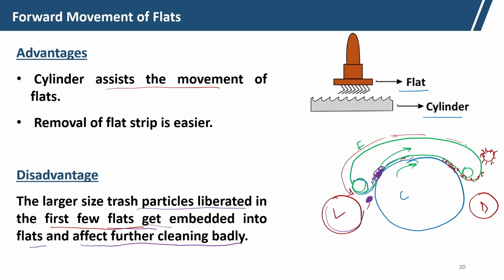If this large size particle is embedded at the initial stage, and this flat is travelling throughout this carding zone, it keeps on affecting the carding action badly, because throughout this travel it is already loaded with the trash particles, and its carding performance has dropped.